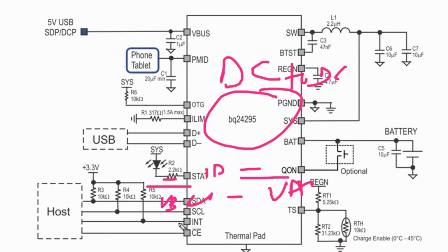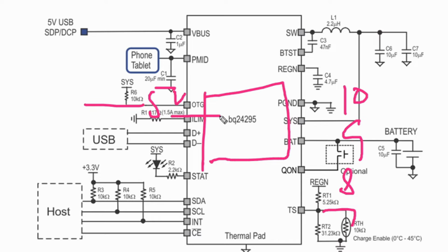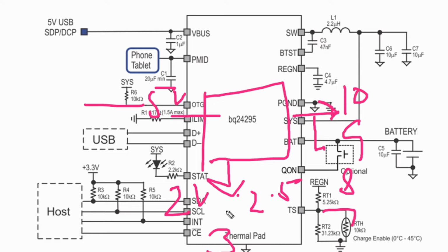Also, it creates step up or step down voltage. For example, if you have an input of 5 volts and your required output is 10 volts, 9, 8, or 7 volts, the DC to DC IC takes the 5 volt input and creates the output you want. If you want 2 volts, 2.5 or 3 volts, it converts to that voltage. That's why we say it converts a source from one voltage to another.